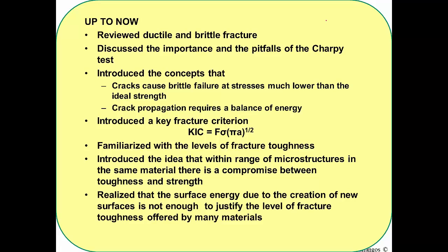So just to recap what we have discussed up to this point, we have reviewed some basic aspects of ductile and brittle fracture. We talked about the Charpy test. That was the way that things have been designed for a long period of time, and we have justified its importance, and also some of the tricky aspects of this test. We discussed the concept that it is cracks that cause failure at stresses lower than not just the ideal strength, but sometimes even the yield strength of a material.